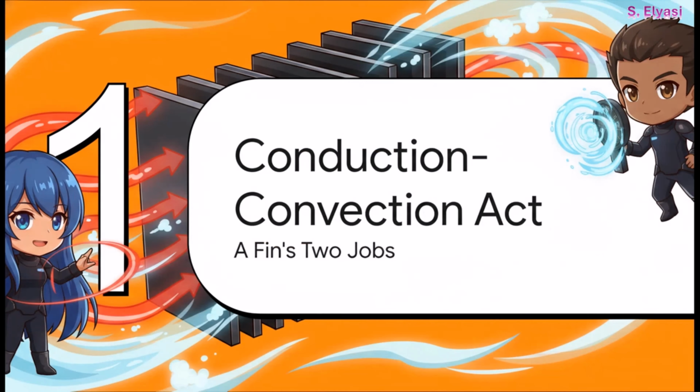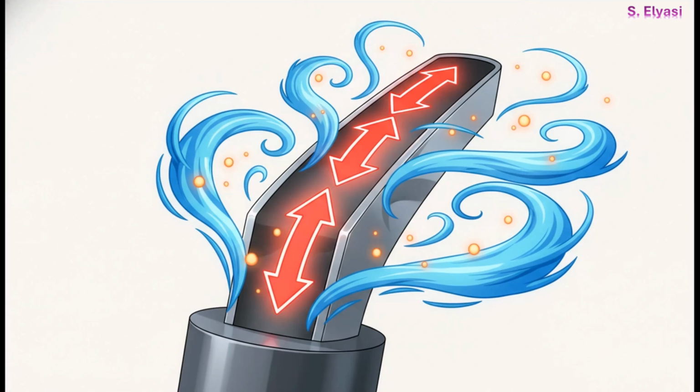The magic of the fin, and it really is kind of magic, comes down to a balancing act. It has to perfectly manage two fundamental jobs in the world of heat transfer. It's moving heat in two different ways at the exact same time. So a fin has two crucial jobs. First, you've got conduction. This is heat traveling through the solid metal of the fin itself. Imagine it's like traffic moving down a highway, going from the hot base out toward the cooler tip.